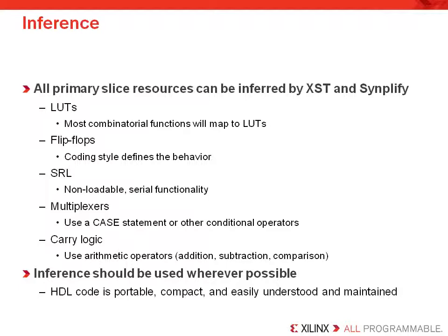In general, inference is best and preferred by our customers. It assures portability to another technology and is, of course, reusable. However, most customers will have to do some instantiation in the design to get all the dedicated hardware they need.